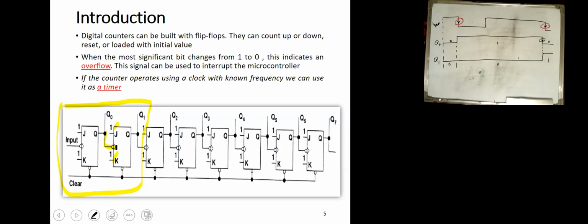So if our counter is triggered by an input that is not periodic, then it is basically a counter circuit. It is just a counter. It counts events, and these events are these edges, falling edges or rising edges. It depends on how the timer is designed. However, when the input is a periodic square wave, our counter circuit, it is the same circuit, is now counting time edges, so it can be used to measure time. It can be used to generate time.